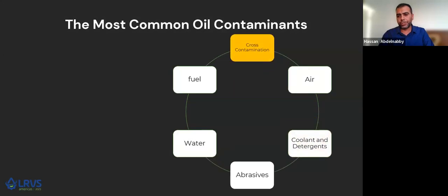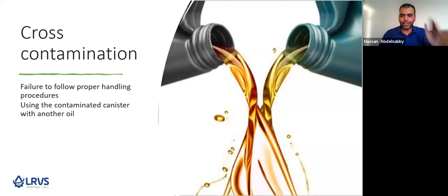So of course, cross-contamination. Cross-contamination can come from bad mentality at the beginning. If you have some remaining oil and you want to fill up the tank and you say that nothing will happen, so let's put it here and see what happens, this can lead to cross-contamination. Both of them may eat each other. The additives themselves can kill each other. Let me rephrase it like this. The oils start attacking each other, and at the end of the day, you have lower efficiency of your viscosity or lower efficiency of the oil film, which creates more problems.